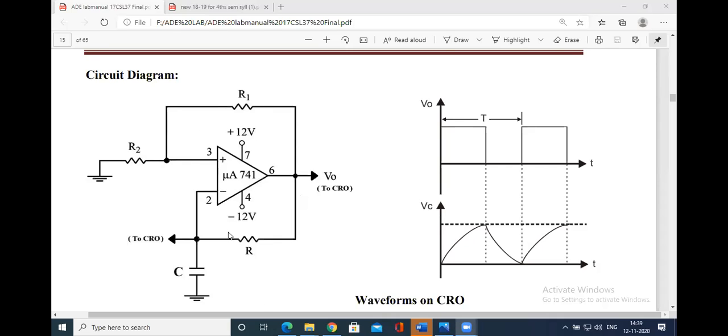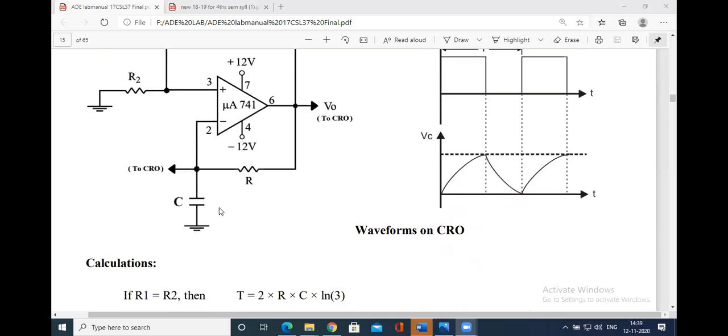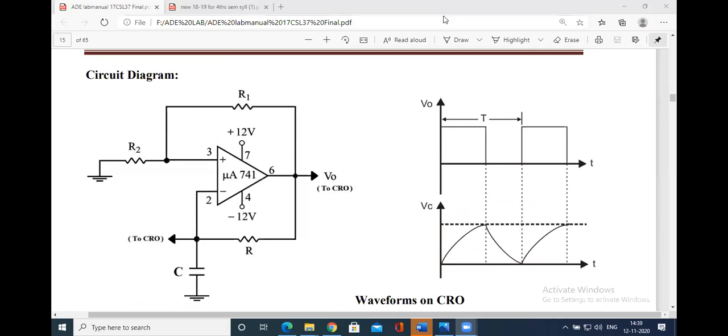Okay, here is the circuit diagram that you use, with the 741 op-amp, right? This is a fixed circuit we have, right? Always pin 2 is connected to the capacitor C. It is 0.01 microfarad. Fine. And we have resistors R1, R2, R1 and R2, right?